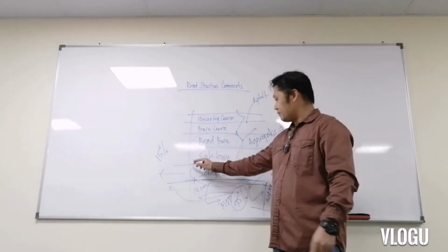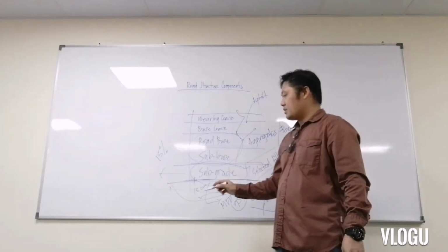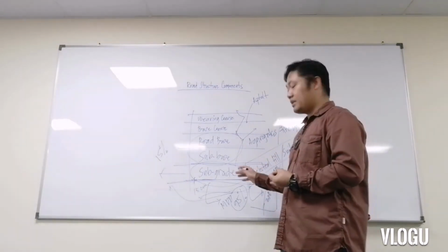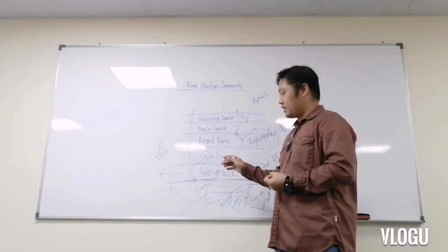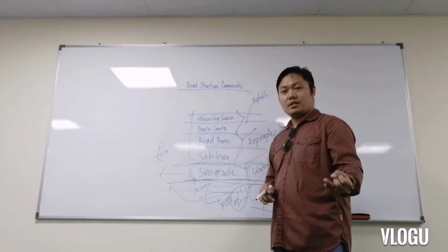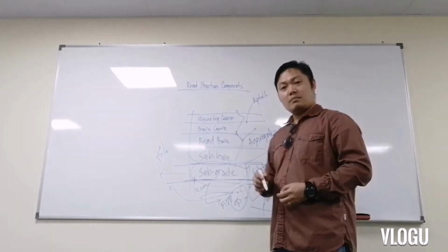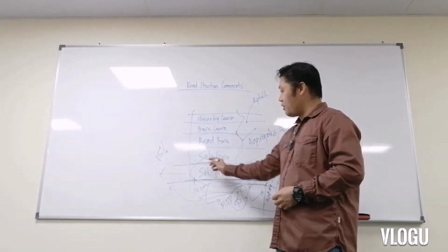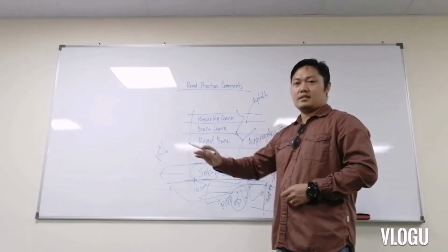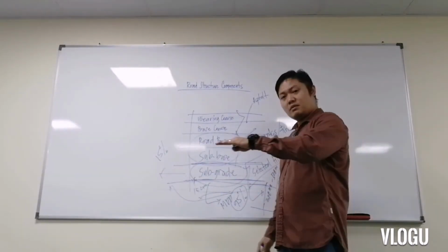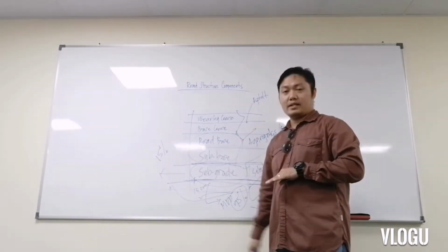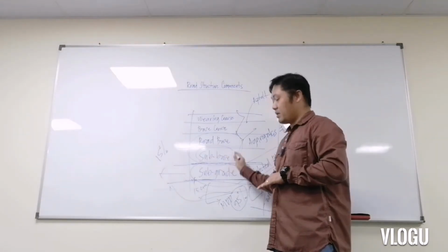Right now, after we attain the final road formation, we have already acquired the final layers of subgrade on top. So we also have to determine the MDD, perform the field density testing, and at the same time perform the CBR, or California bearing ratio, testing. Then we also have to do the surface evenness test. With surface evenness, we determine the evenness of the layers before we lay the next succeeding layer, which is now the subbase.